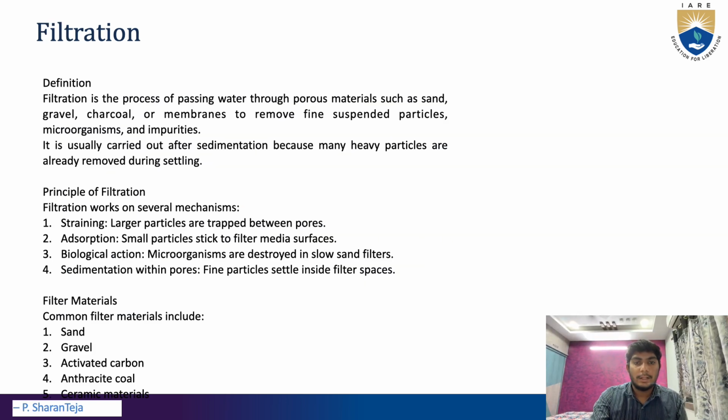Filtration. Now let us move to the second method, filtration. Filtration is the process of passing water through porous material to remove fine impurities. Common filtration media are sand, gravel, activated carbon, charcoal, ceramic, and membranes. Filtration is usually done after sedimentation. Principle of filtration. It works through several mechanisms like straining, adsorption, biological action, and sedimentation.